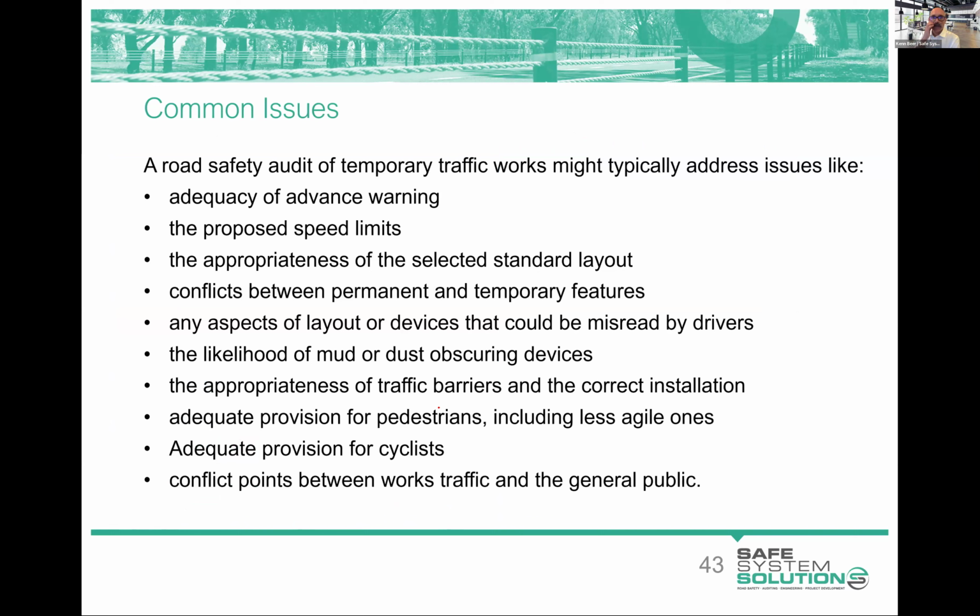So listed here are some of the common issues that may arise in road safety auditing of construction sites. By no means is it everything, but the first is the adequacy of advanced warning. I always stress, you've got to be able to understand that it's coming up, but you've also got to be thinking about the queuing of vehicles and where that goes, whether we can see the end of the queue, and whether we have provided enough advanced warning.